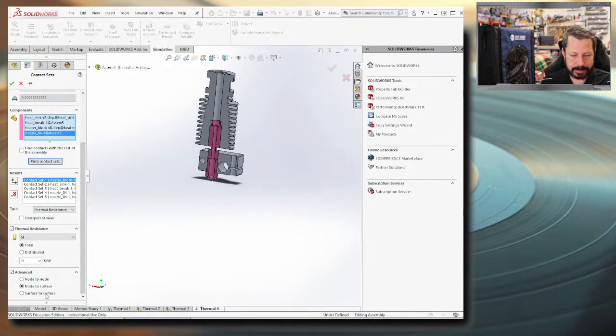Oh, okay. Yeah, this is talking about how in the mesh, how is it going to work. And the default is a node on the mesh to the surface it's contacting. And so node to node, I imagine, would probably be faster simulation wise, and surface to surface would probably be slower simulation wise, but the node to surface in this model didn't take very long to do.